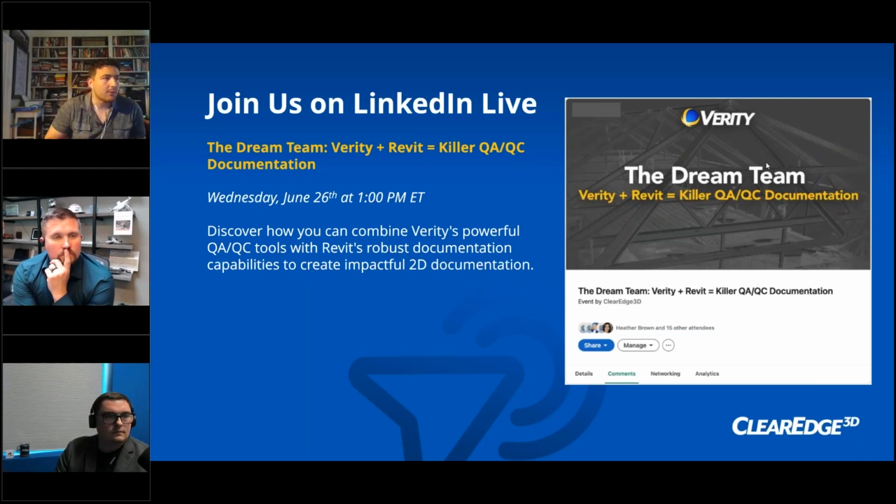So at the moment, working with SLAM and construction verification, currently it is in beta. If you're interested in trying that out, the results I've seen working with the VLX have so far been pretty good. I will say there are some limitations on object size. Again, SLAM data just tends to be a little bit fuzzier. So working with smaller pipes and smaller objects, the results can get a little interesting for the fitment.